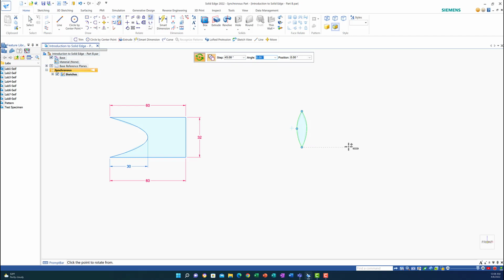Make a horizontal line, and then move 45 degrees. That's good enough. Okay, I'm going to click, move another 45, click, then move another 90 degrees and click. So now I was able to create a rose. Let me scale it here, and you can make it larger if you want. So I was able to create this Rosetta of 4 leaves.